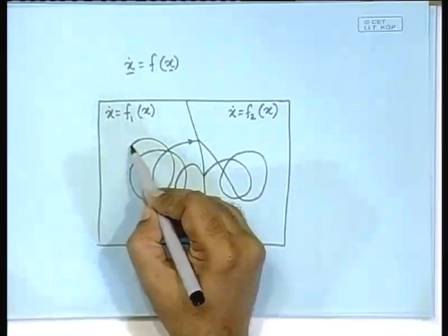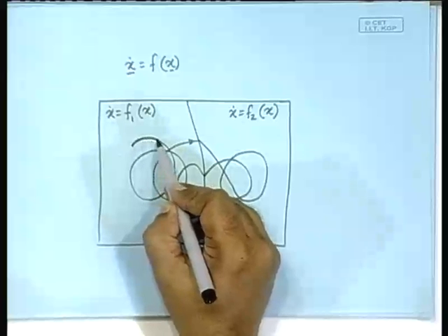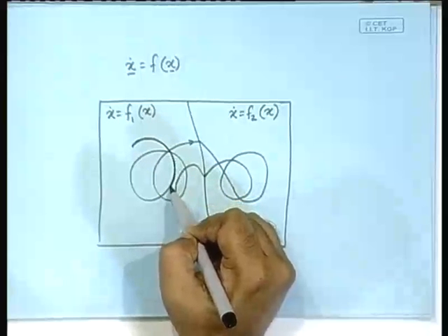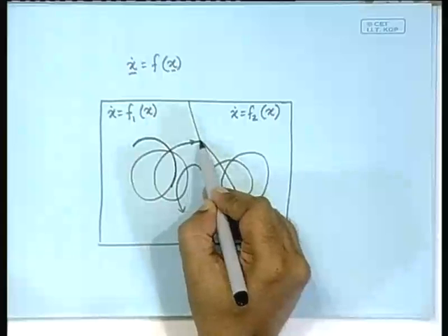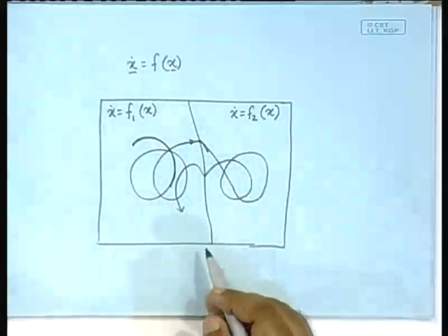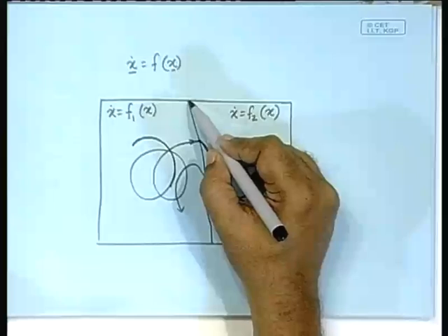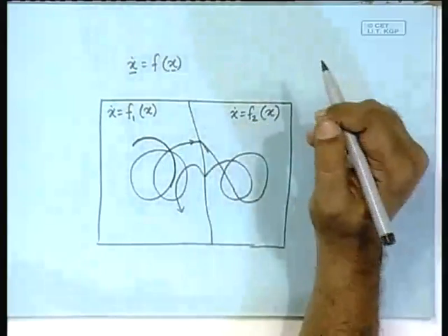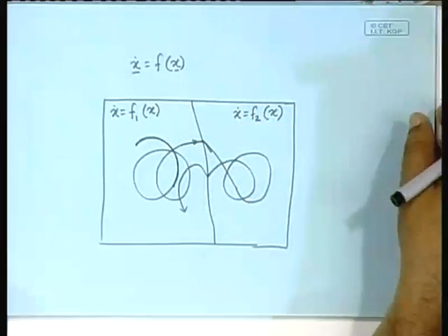Notice, smoothness relates to differentiability. Now, here when it goes within this compartment, at every point it is differentiable, this curve is differentiable, right. But the moment it hits and goes in another direction, at this point it is not differentiable. So, at this surface, the switching surface, the behavior is called non-smooth. This word non-smooth should be understood. It means that it is not differentiable on a specific surface or a switching plane.